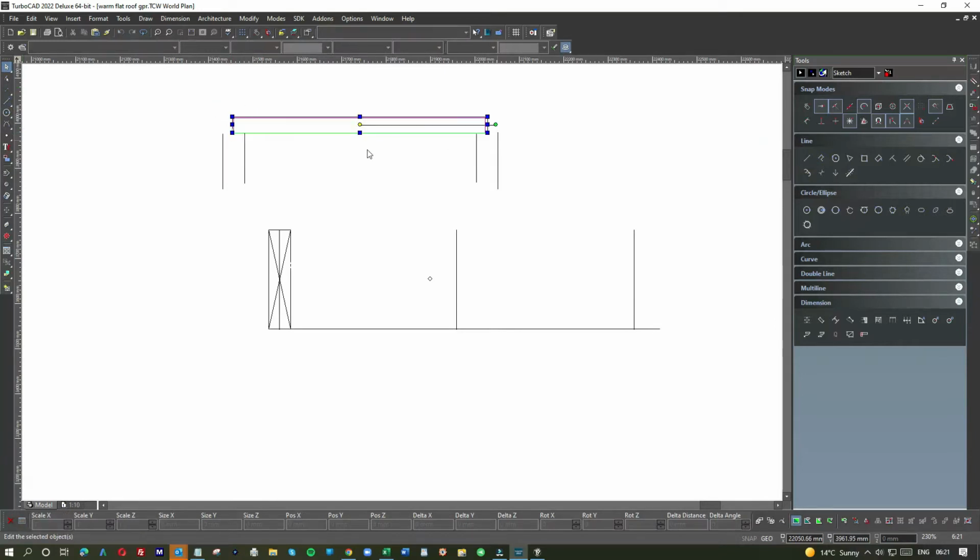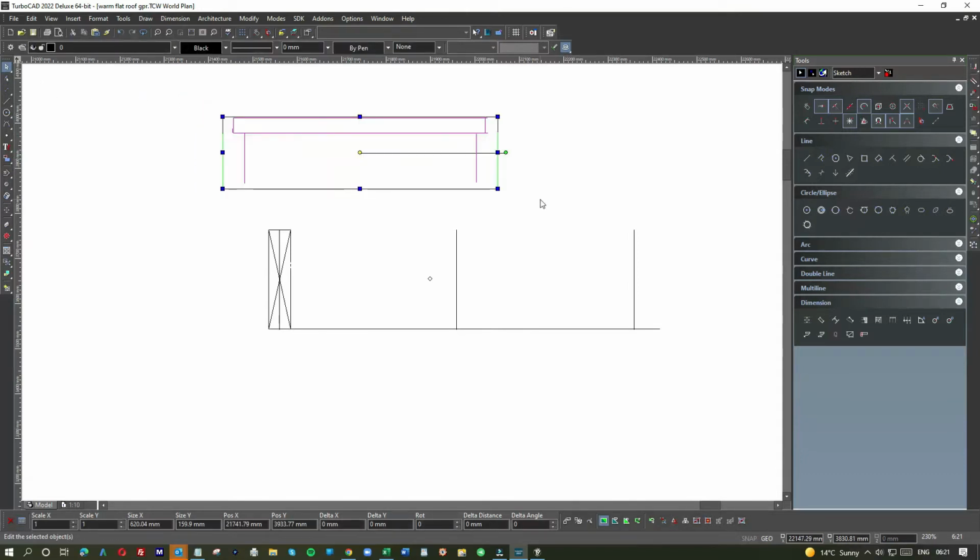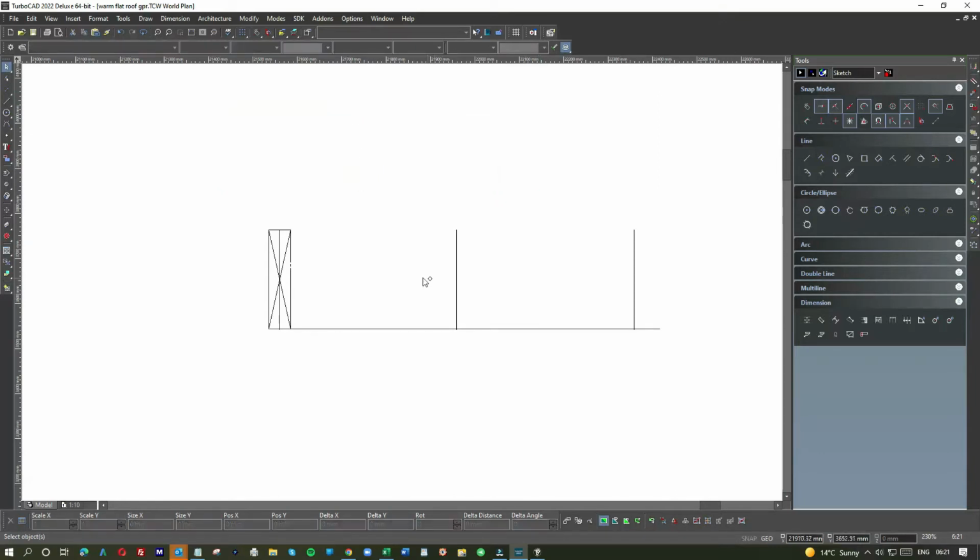A 7-inch beam. So if it was 10 foot wide, you go half, which is 5, and then add 1, a 6-inch beam. If it was 8, it would be 4 plus 1, which means a 5-inch beam. So you get the drift. That's a general rule of thumb for the thicknesses of the actual roof joist.